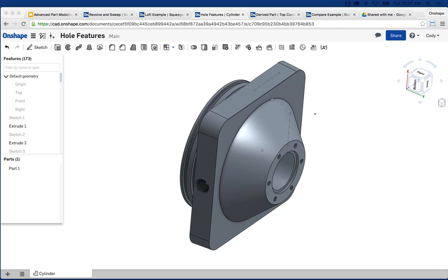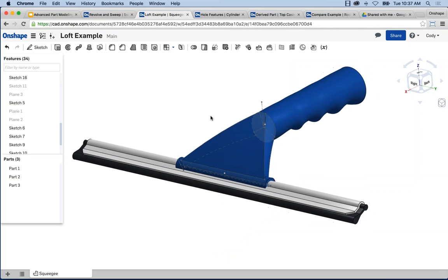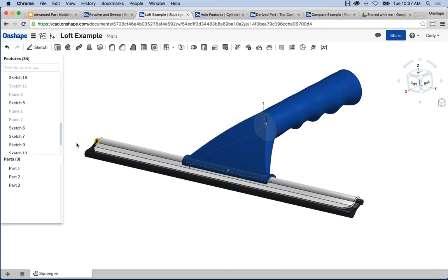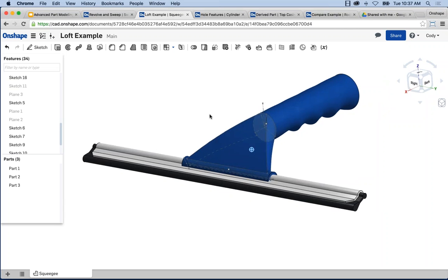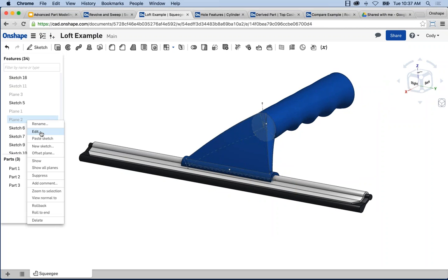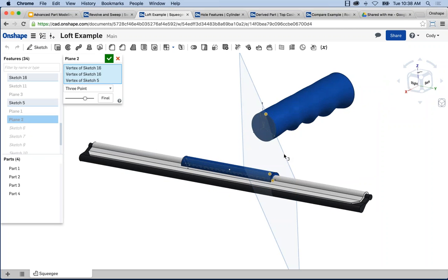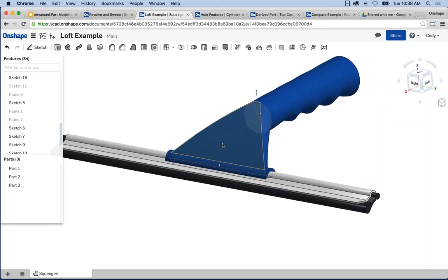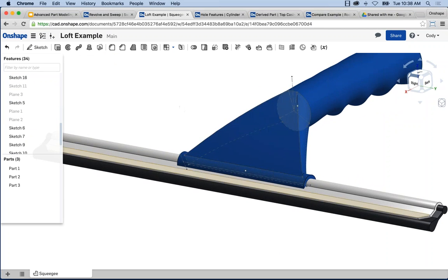Question from earlier. So if 120 degrees changes, the planes change. There was not 120 degrees defining those planes from earlier. Forgive me if I'm confusing this with something else. The planes that I created earlier were referencing 3 points from sketches. So if those points change, yes, this plane would change. But there wasn't a 120 degree value.